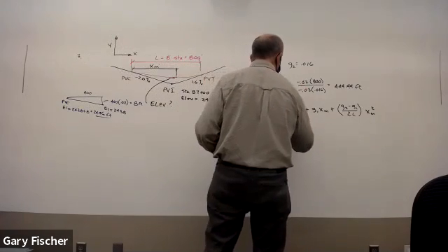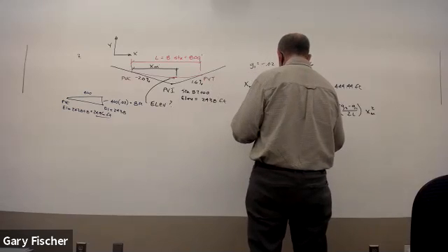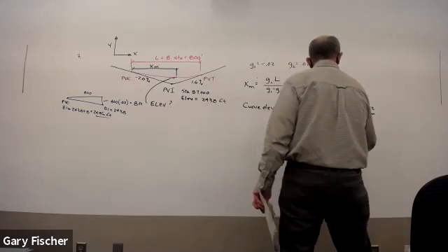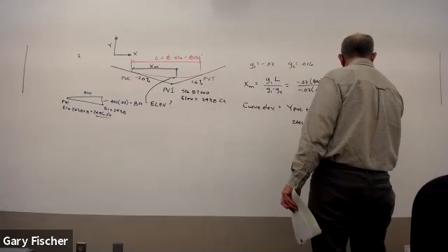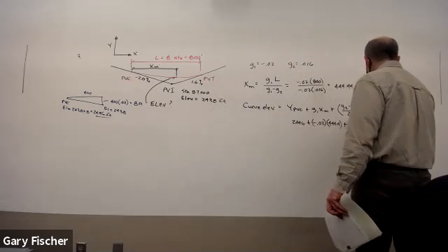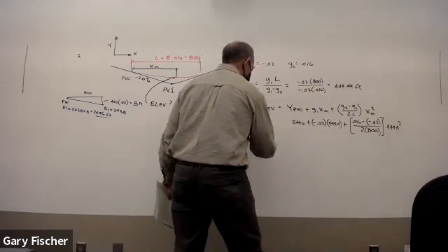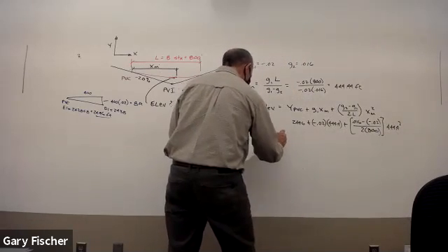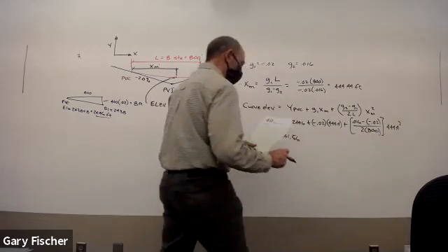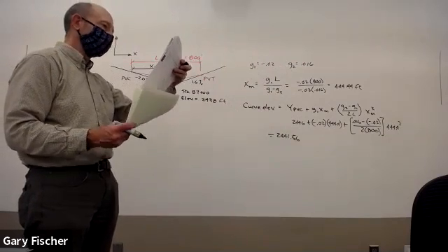If you plug in all those values, this is 2446, that's the elevation, plus negative 0.02 times 444.4, plus 0.016 minus 0.02 divided by 2 times 800, and this is all multiplied by 444.4 squared. The curve elevation is going to be equal to 2441.56. Where they give you 24, so it'd be C.